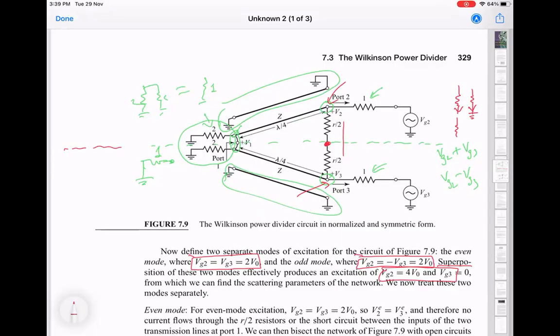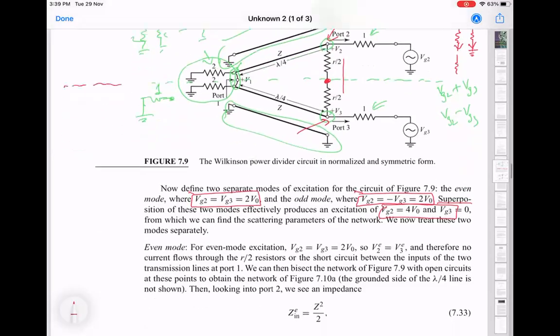And again, to reiterate, even though the normal mode of operation of this device, which is the splitter, is you put the input on the left side and take the output on the right side, we are actually doing the calculation the other way because it's easier to analyze the system. And because it's symmetric, you expect this network to be symmetric. You can essentially, if you calculate S12, know that S21 is the same as S12. So the analytical calculation will allow us to derive these ideal S matrix elements. That's exactly what we are trying to do.